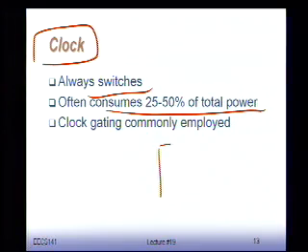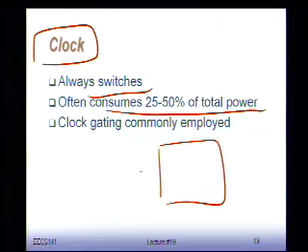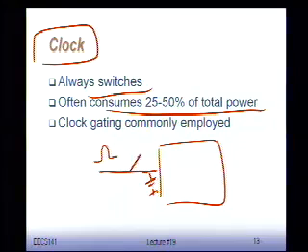So here I have this big multiplier. If you look at it from a clock signal perspective, there's a big fan-out capacitance hanging in here. Definitely if it's a dynamic one, all those pre-charge and evaluate transistors hang off from there. So it's a good idea to disconnect that when you don't use the block. The way you disconnect it is typically using a gate which just enables or disables the clock. This way this thing doesn't switch anymore. Very, very simple. But remember this when you want to do power, even though in the project we're not going to turn things off, so it won't help you very much in the project.